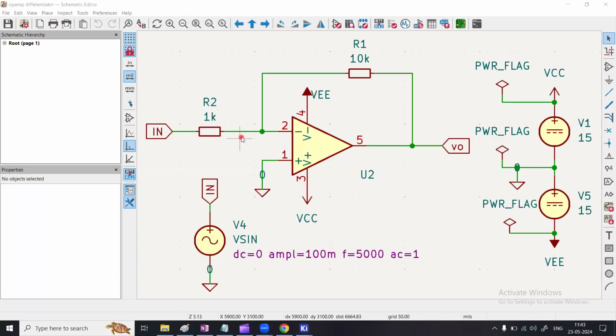Okay, so finally, I will show you how to perform an operating point analysis for the circuit. As I said, the operating point analysis will enable us to find out and understand all the voltages and the currents of this circuit based on how we have biased it. As I said, you have plus minus 15 volts applied to the positive and negative power pins of the op-amp respectively. You have the input voltage source at the input of this operational amplifier, and then you are recording an output. So all the currents through resistors, voltage across the resistors, voltage at the output, voltage at the